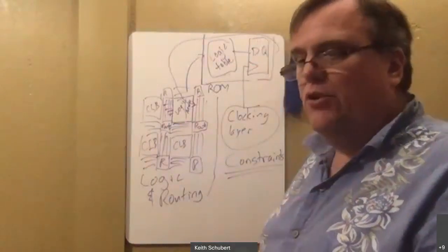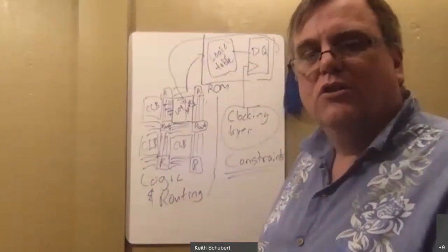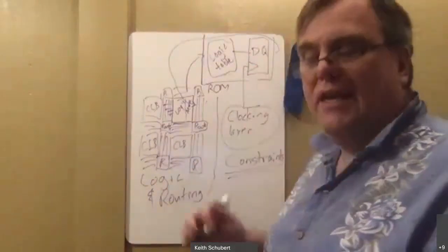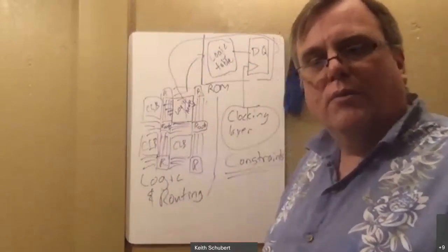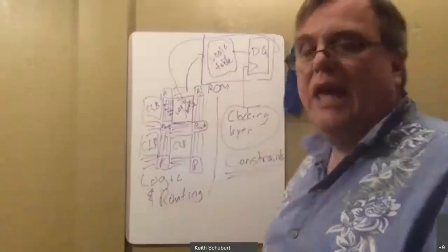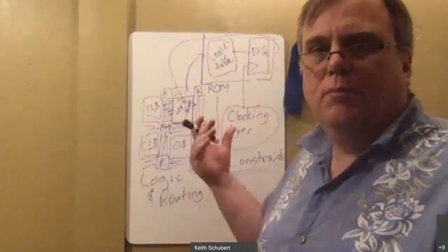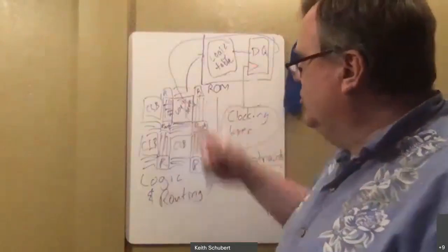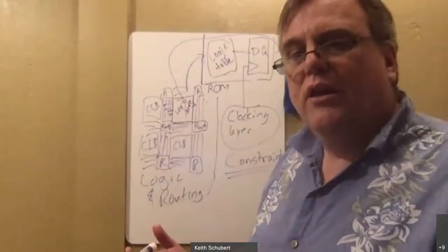You should only ever use a designated clock signal to time a D flip-flop inside an FPGA, because that's just a requirement of how the system is built. If you've got an individual component, you can deal with it. It's still dangerous, but you can do it and you can do it better. The FPGA just has no way to do it, so it has to fake it and it just becomes really ugly.